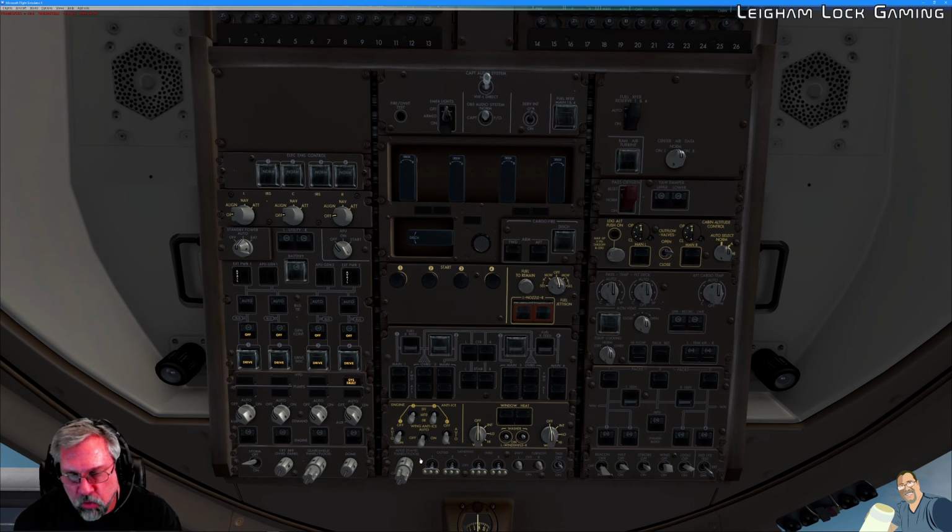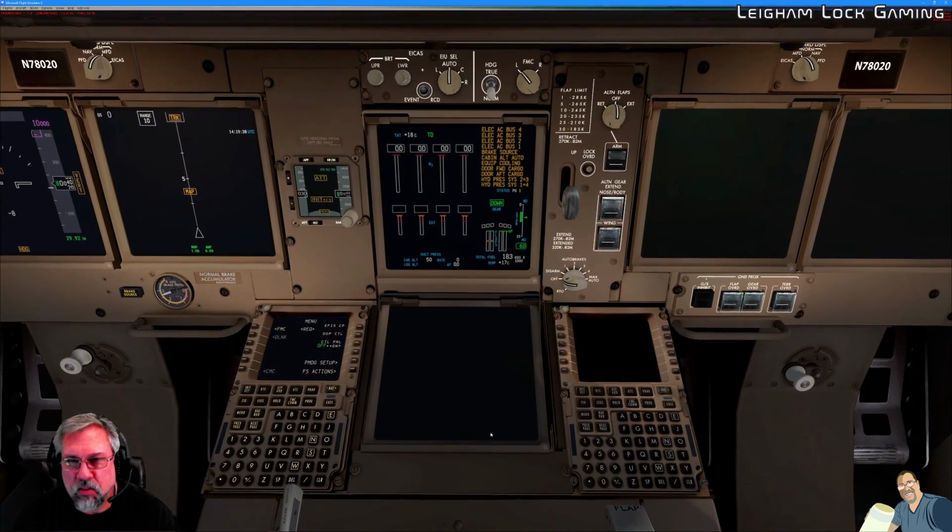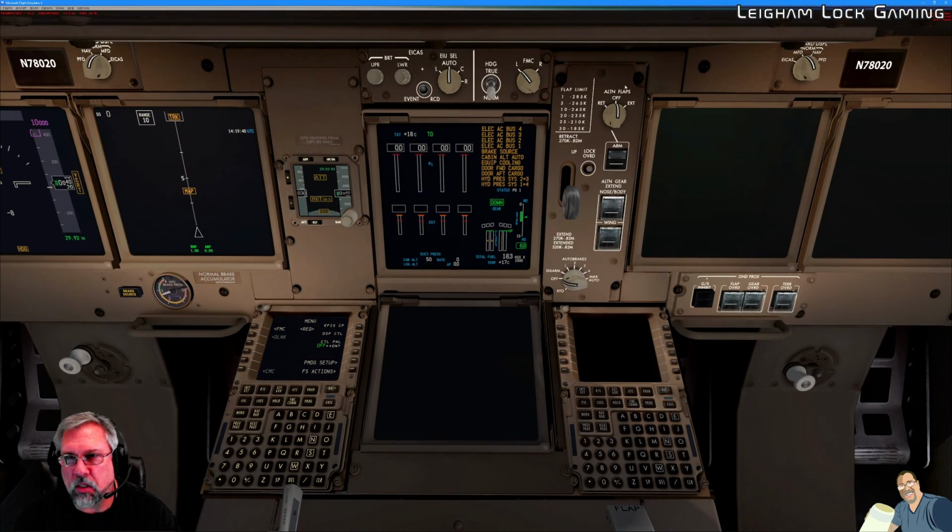We also want to take a look at the windshield wipers. Make sure they're both in the off position. Drop down and check the alternate flaps configuration. So here's the alternate flaps retract and extend control. It's not armed, so it's not drawing electrical power. Confirm that our landing gear is in a down position and the lever is in the down position. And you can see here on the ECAS page that it also indicates gear down, so that's good.